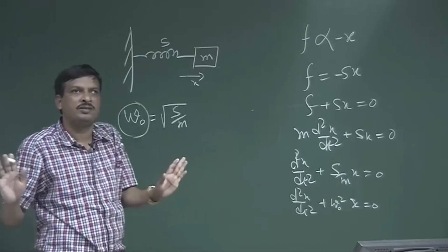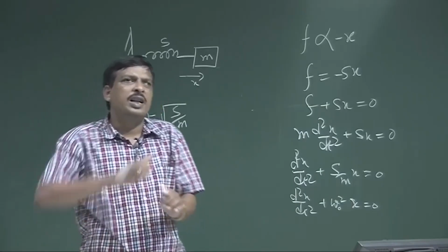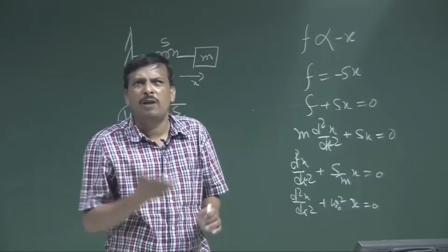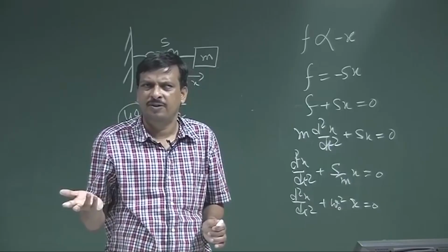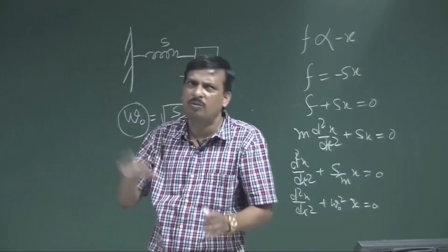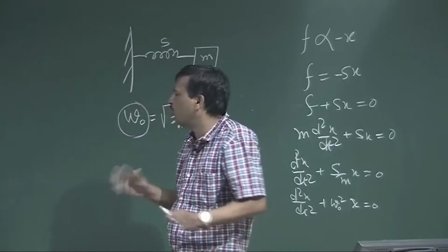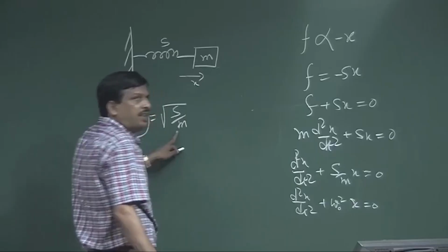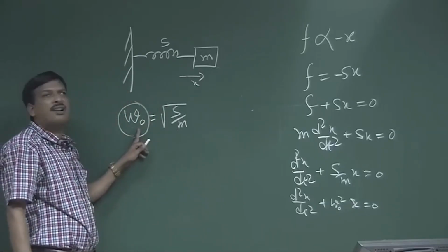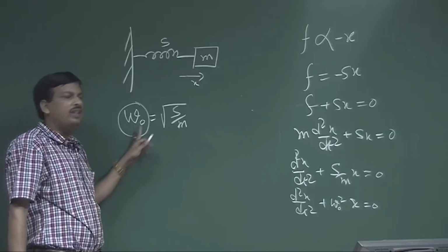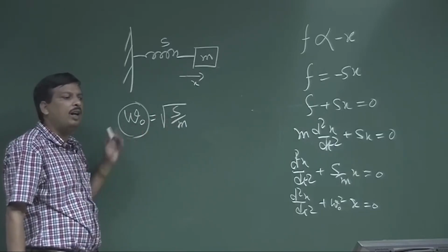You know these things. Okay. So, that means a huge microphone may not be able to produce the high frequency. We will understand why it does not produce the high frequency and what extra arrangement we should make. Those things are done in the microphone design. So, you should know the physical meaning of natural resonance frequency: increased mass, natural resonance frequency low; increased stiffness, frequency high. Okay.